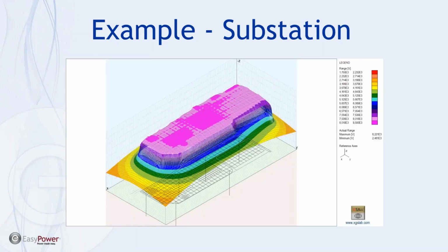This visual shows the ground potential rise with the proposed grid design. This is during the design fault that we've applied, in the soil model that has been applied with the preliminary grid design that is shown below. You can see the grid and some ground rods that are going down in the Z direction from the grid. This is a nice visual because you can see that the grid area, the elevated area in pink on the GPR chart, is brought together up onto an equipotential plane.